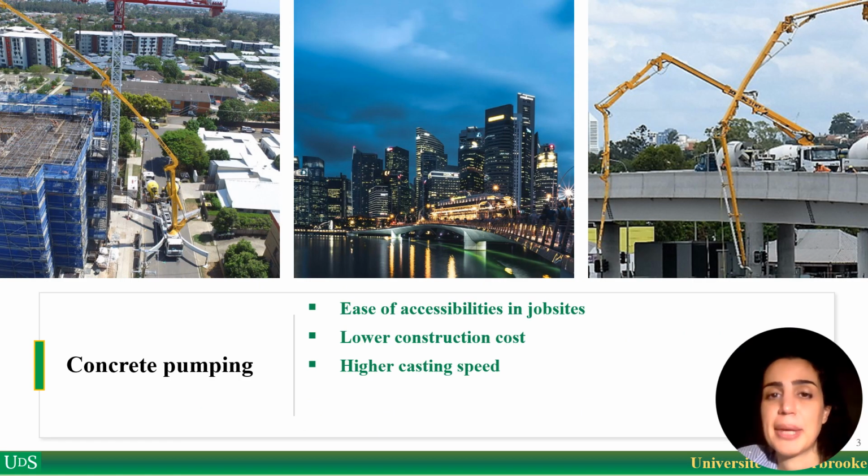Concrete pumping brings many advantages for the construction industry. For example, it helps us to put concrete in very difficult access locations of the job sites, and this feature is very important to build tall structures. Also, it increases the quality and the accuracy of the building. However, sometimes failure can happen. For example, pipe blockage is one of the most frequent problems that may occur during the pumping process.